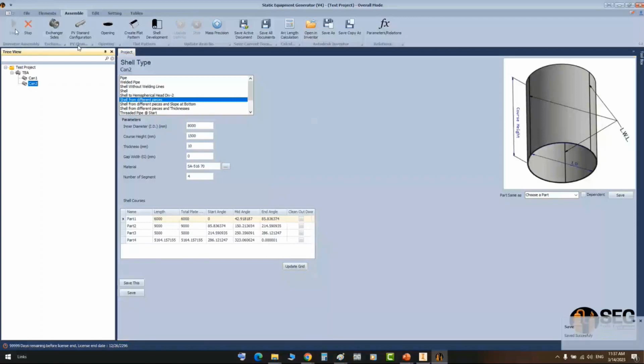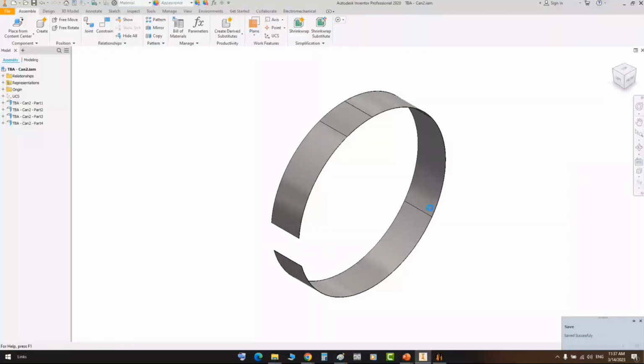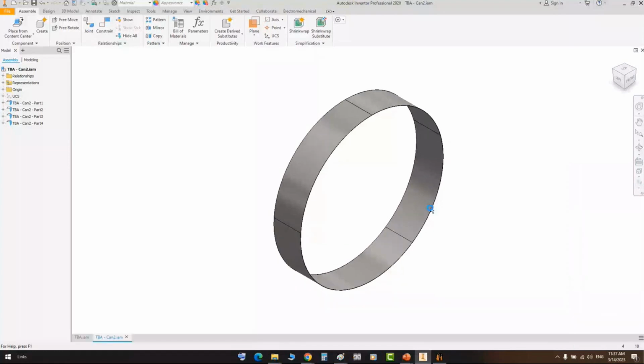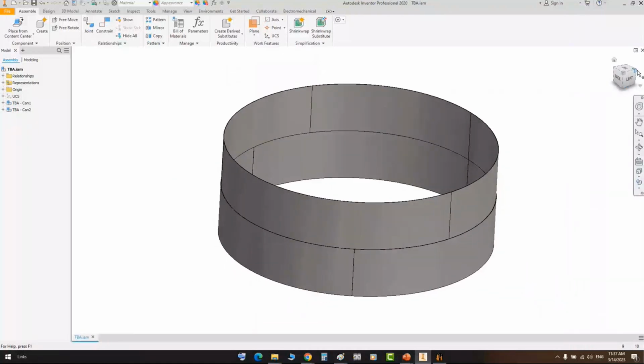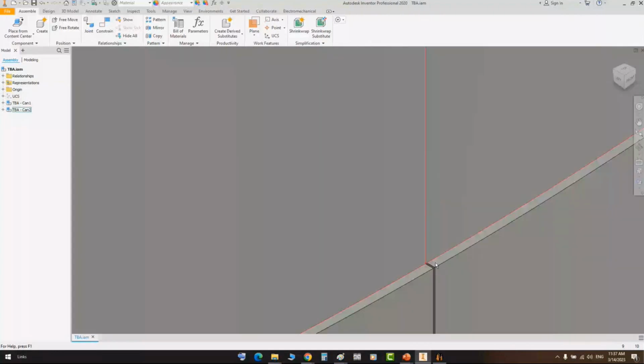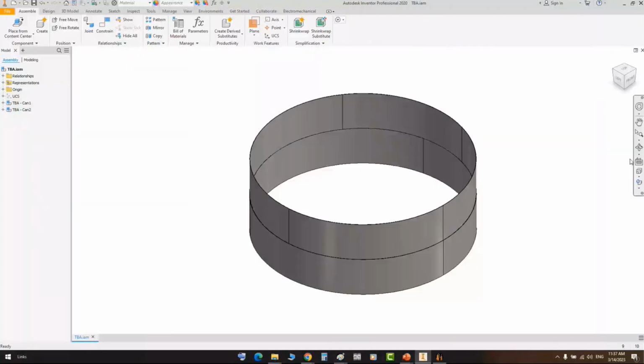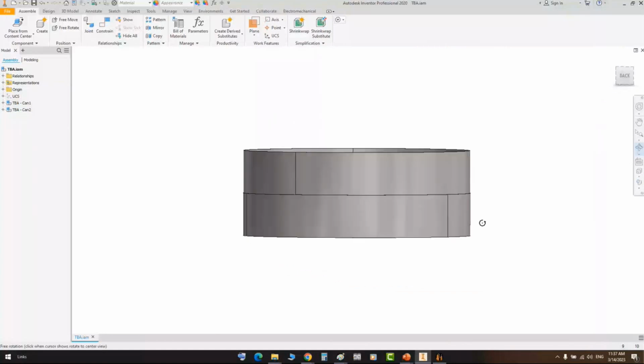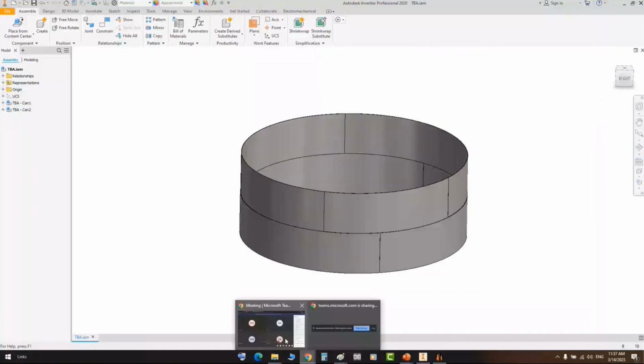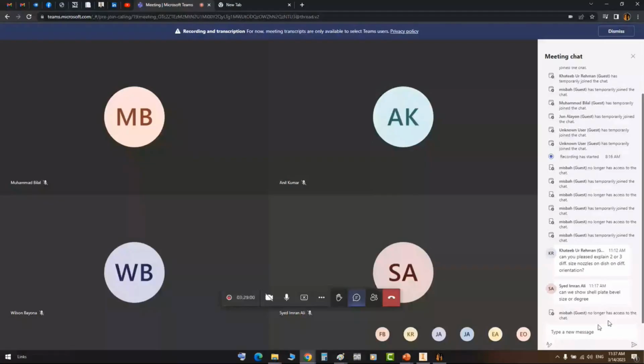Now when you click Start Assembly, you can see that you get a clash between some vertical longitudinal welding lines, because we gave them the same orientation. At the bottom shell, we made it 0, and in the top shell, we made it 0. If you take a look from the front, you can see that you have the same longitudinal welding line orientation at this part. Okay, I hope now your question is covered. Yes, this is clear. Okay. Any other questions?